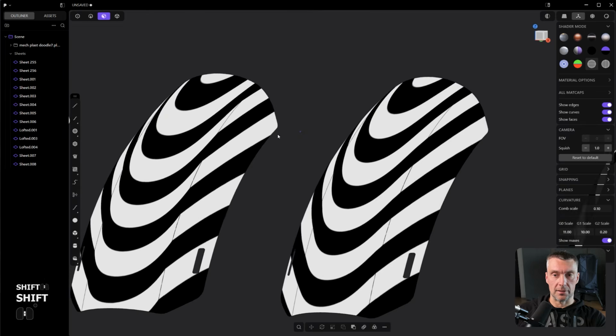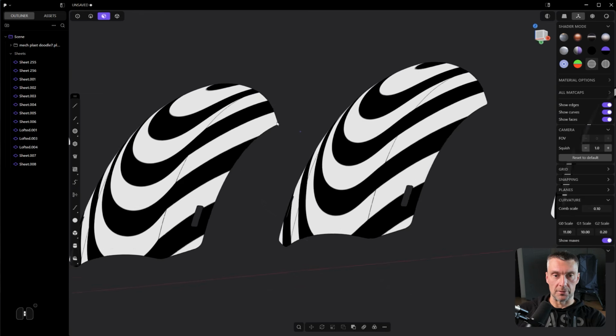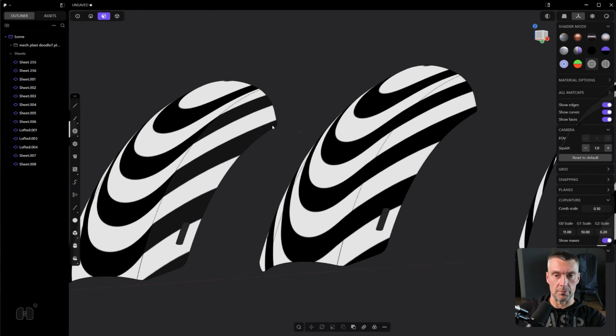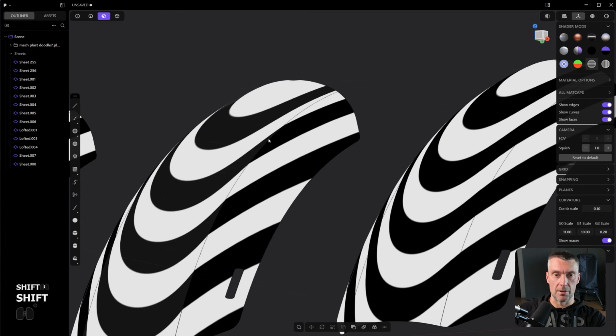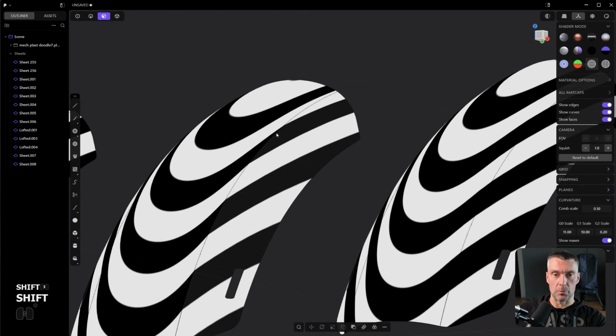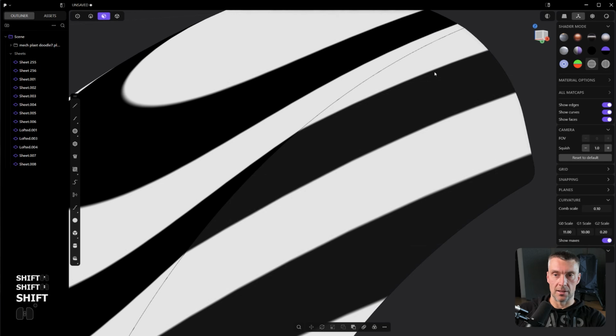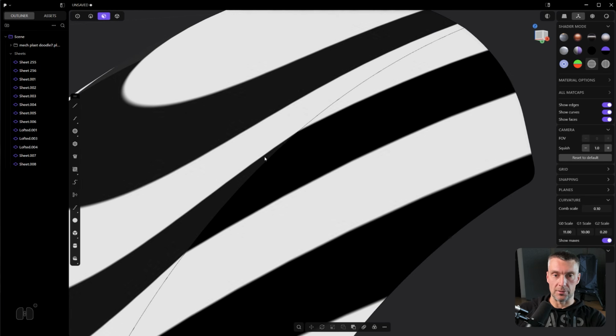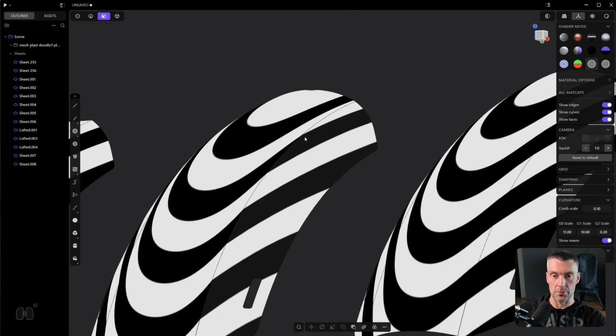If I manipulate the zebra and rotate in the viewport, you see that there is a very different angle here between these two on this edge, right? You can see the line continues like this here, and then abruptly shifts into an angle, and this angle between this line and this line is definitely not smooth, right? It's a bit of a sharpish angle. So it looks smooth, but it's not really smooth, right?